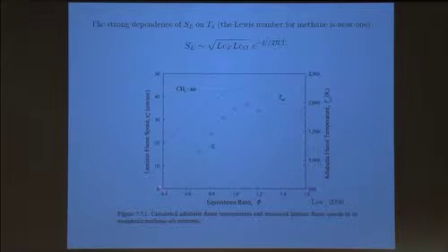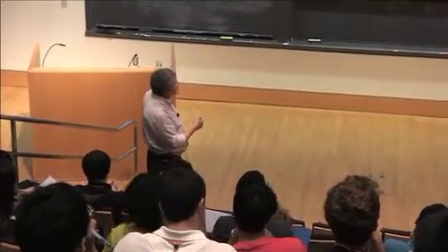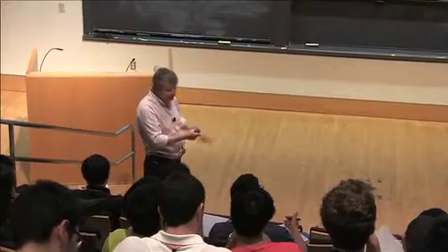Here is the graph of the laminar flame speed as a function of equivalence ratio. There is a measurement of flame speed, and there is here essentially a calculated adiabatic flame temperature. The measured speed, calculated flame temperature, right. And so first of all, this is for methane, and we know that for methane the Lewis number doesn't change very much from the lean to the rich side. It's very close to 1 across the entire region. And therefore, you can see that there is a correlation, in fact, between the flame speed and the flame temperature. In other words, there is no shift, as I suggested.